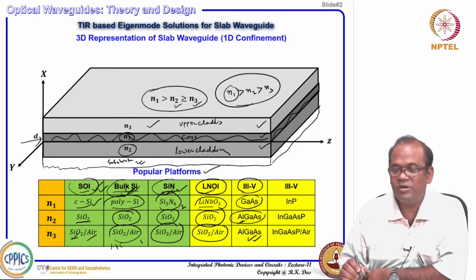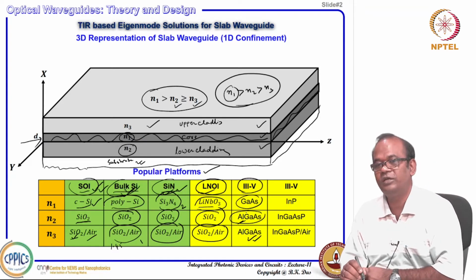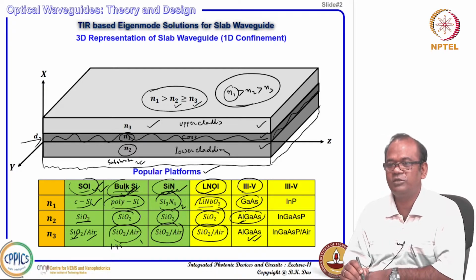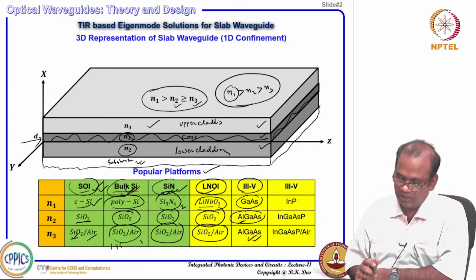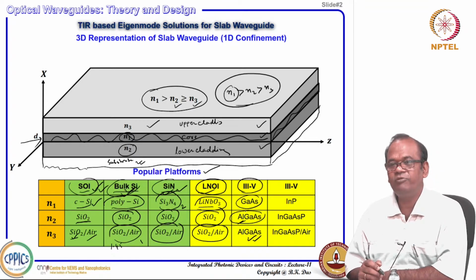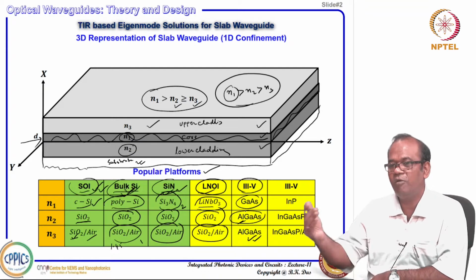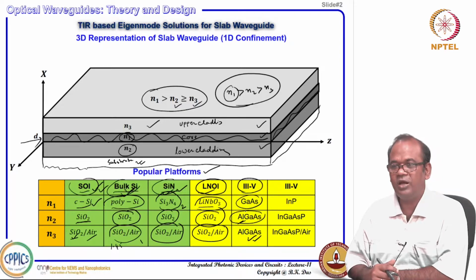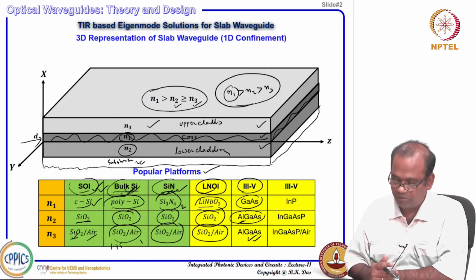Similarly, gallium arsenide is basically used for laser diodes, photodetectors, all those types of things. It is a direct band gap semiconductor, so it is useful. However, if you fabricate a gallium arsenide laser, typically the emission wavelength does not satisfy your communication band of 1550 nanometer, rather it is around 1 micrometer, less than 1 micrometer.